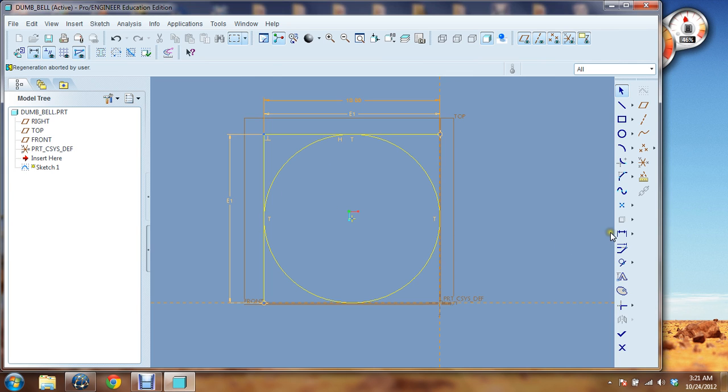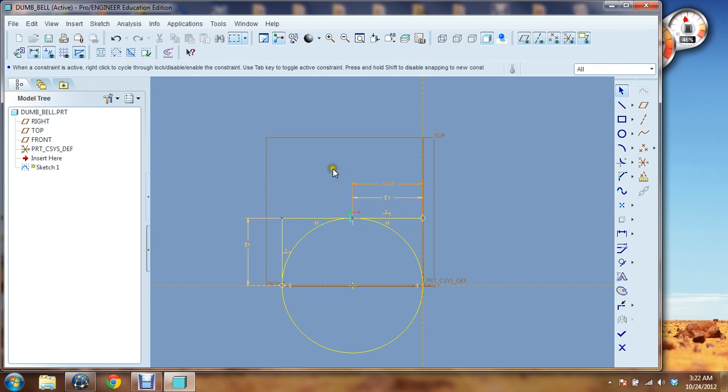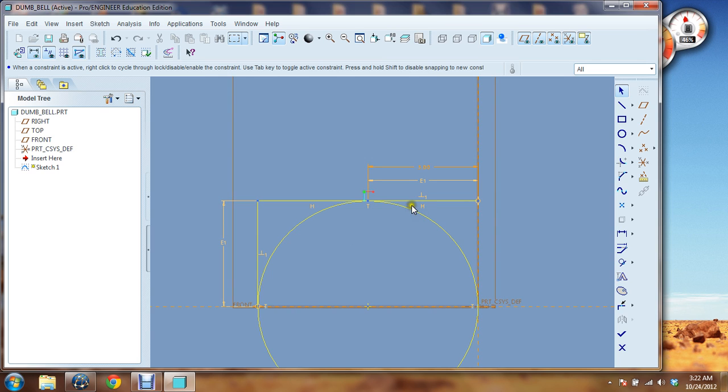So back over here on the right side, notice we went over these tools. What I want to use is this divide tool. This is going to break a line, one single line to create two lines. We're going to click that, and I want to break it where this is tangent, on this tangency point, that exact point. You may notice it doesn't lock very well to that, but if you do get close to that tangency and click it, it will break it. Now, you notice I broke it, and I'm going to middle mouse click to get out of there, but now something has changed.